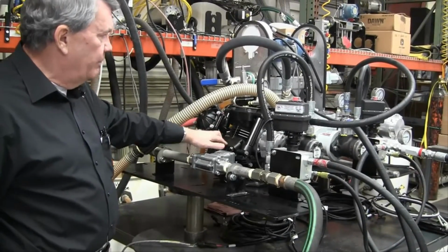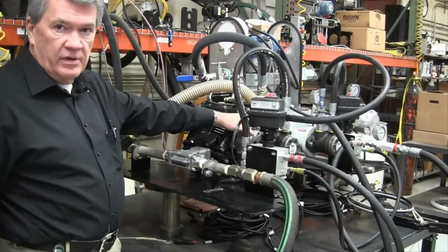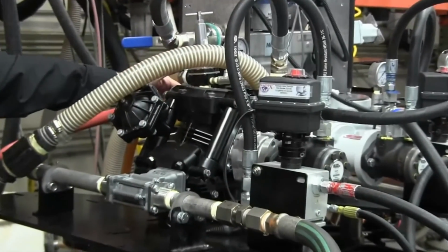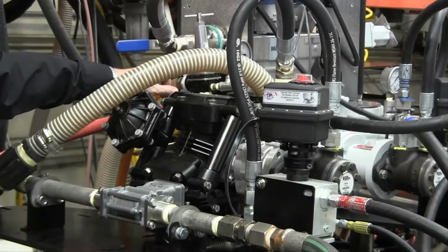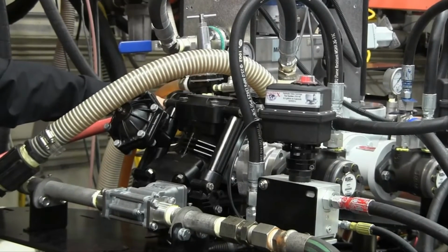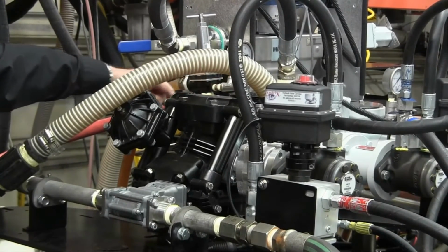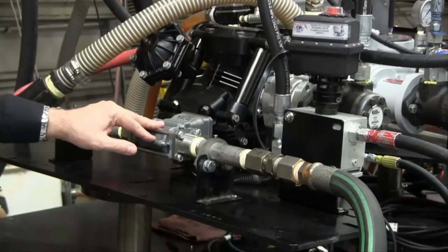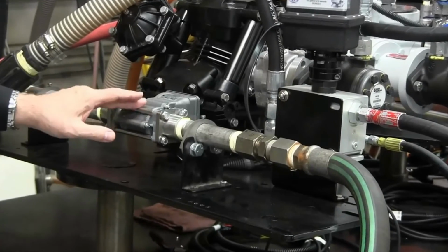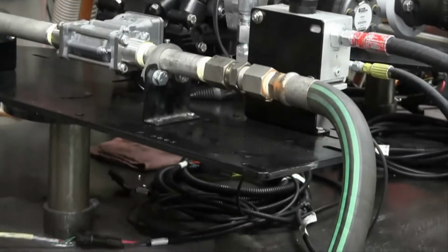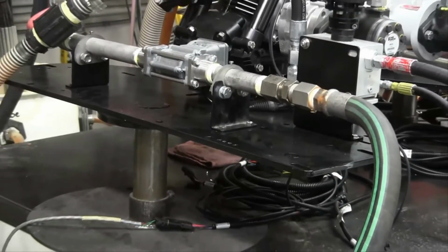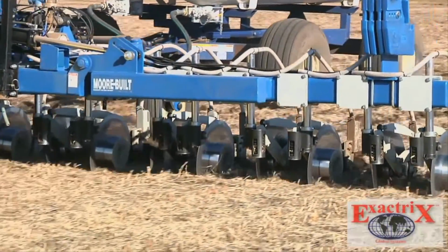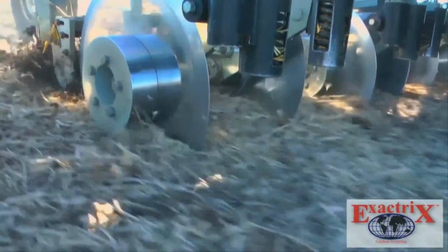So this is the pump, the hydraulic motor. There's a tachometer circuit here. The flow is coming out of the pump past this bypass valve. You see the bypass valve, a little pressure gauge there. It comes around and through this flow meter. This is an Arag flow meter. On out past the flow meter, it goes into the manifolds and injects into the ground, as we showed previously, the two orifices coming together.